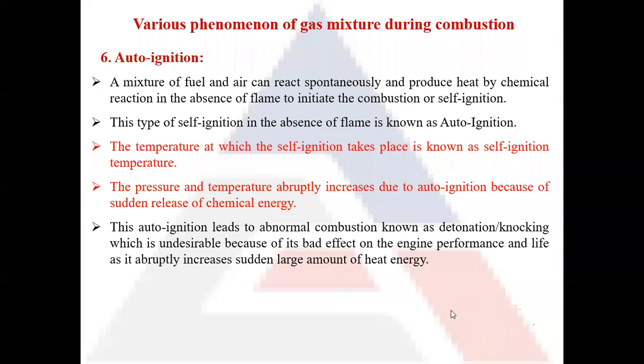When these flame fronts collide, they cause a lot of sound, a loud metallic sound, and there are vibrations. These vibrations and sound are very damaging for the various parts of the engine.